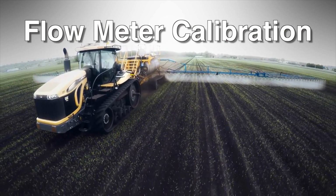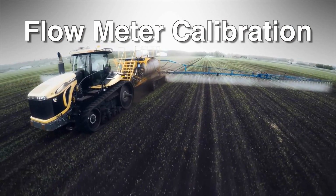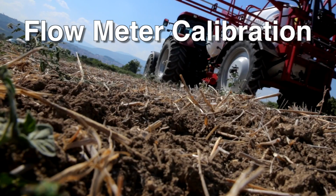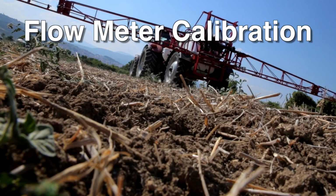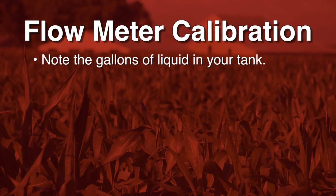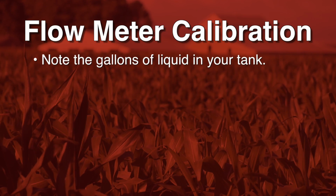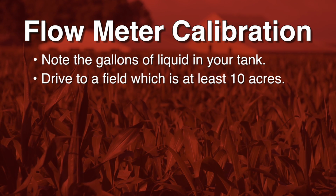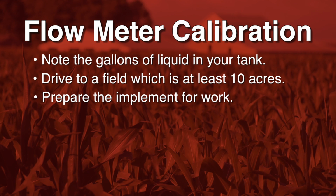Calibration must be performed during normal field work. This means that you can only calibrate the flow meter once the other system parameters have been configured. Follow these steps for flow meter calibration. Note the gallons of liquid in your tank. Drive to a field which is at least 10 acres in size. Prepare the implement for work.